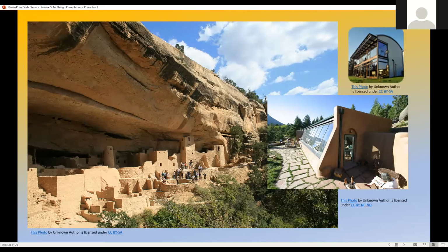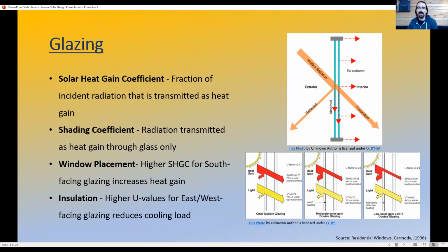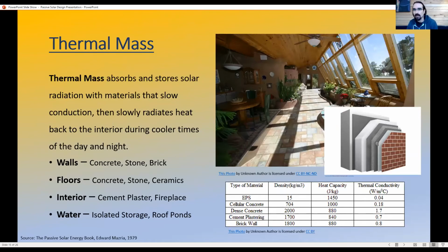Well, this last slide here with the adobes, are those window-looking things, or would those be the solar, what you call it? Actually, no, in this picture, this is just glazing. You can kind of see in through here. And actually, it's the same building as this. So that's the inside of the last picture you were seeing there, where those are the adobe walls. These windows are angled to capture as much of the direct sun exposure as possible in the winter, and then there's a thermal mass in the floor, thermal mass in the walls that collects and radiates that heat back to the space.